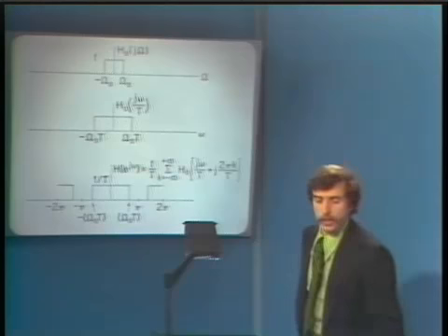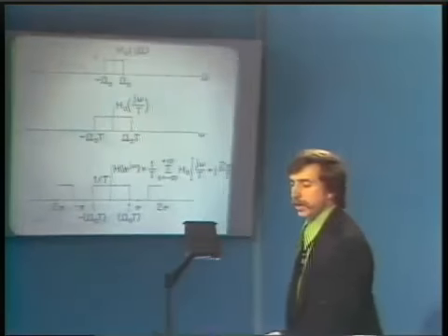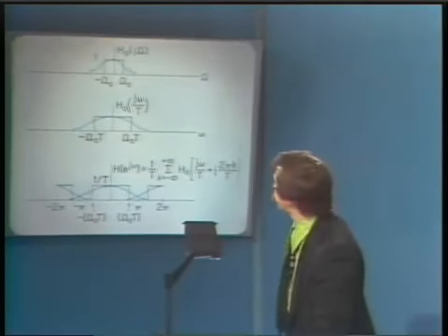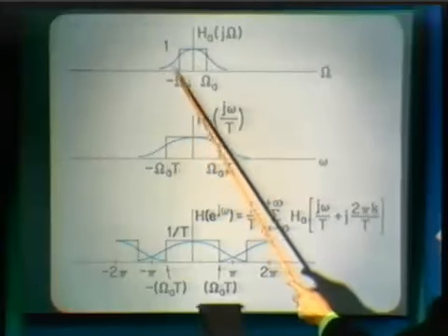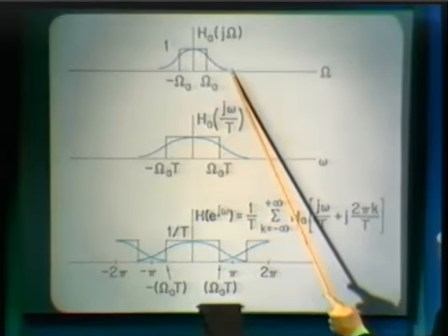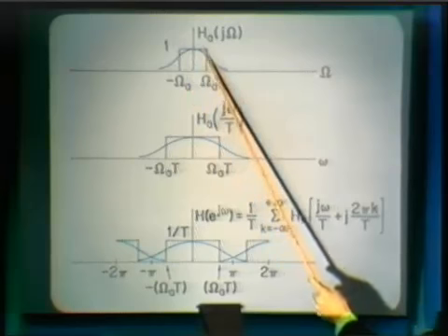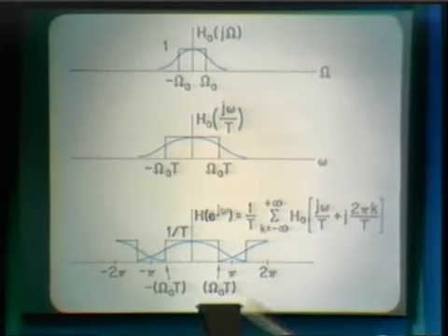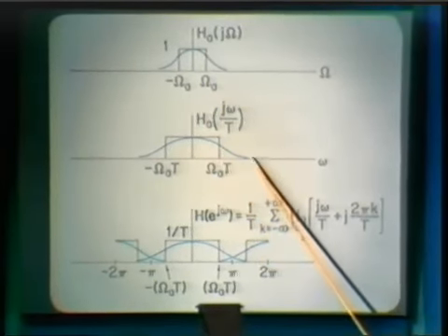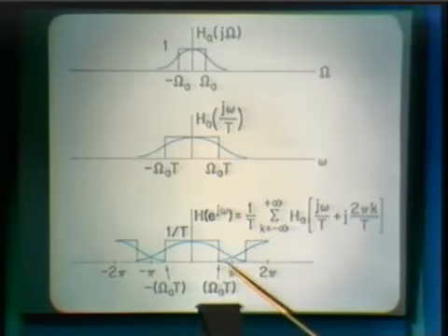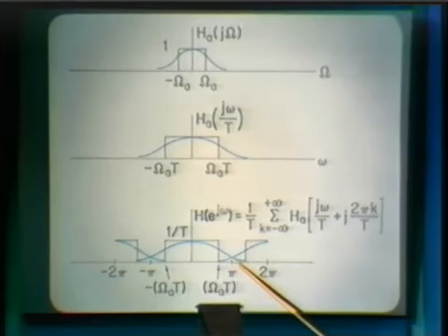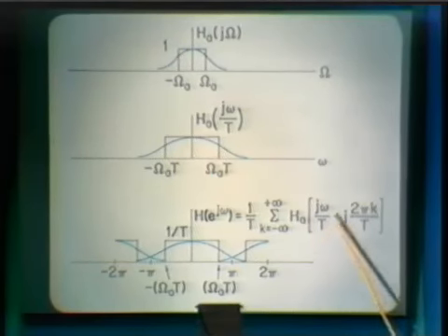But more generally, the kind of frequency characteristic that we would have would look perhaps like this, as an approximation, admittedly a somewhat crude approximation, to this ideal low-pass filter, in which case, as we add up the replicas of the scaled frequency response, we, in general, will have interference or aliasing between different terms in this sum.